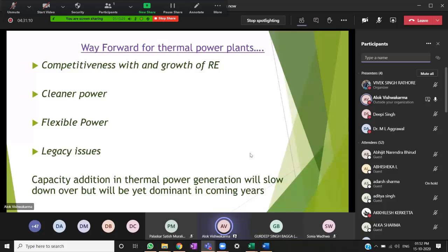When we put this entire energy at the switchyard, from there it is connected to another substation or other lines. For example, a 400 kV transmission line will go to some other substation of the transmission companies. From there, depending upon the power handling capacity, there are state government substations. Suppose it is a 66 kV substation. Depending upon their infrastructure, it is further stepped down, and ultimately for households we need 415 volts.